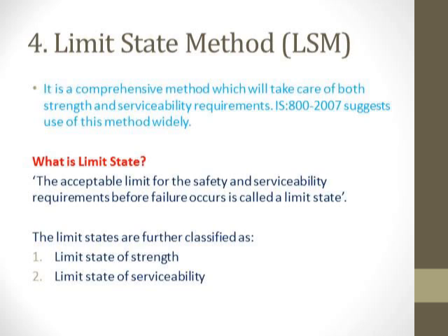This is further classified into two limit states, that is, the limit state of strength and serviceability. While considering this, the designer has to ensure that he designs for fitness for purpose, safety, economy, and durability of the structures. Uncertainties should also be taken care of regarding the loading, material strength, structural dimensions, and the behavior of the structure. So now let's discuss the limit states of strength and serviceability in detail.